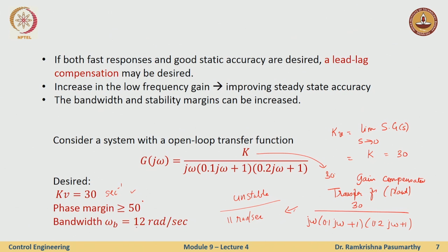So the specifications are usually in terms of the closed loop bandwidth, and in the previous lectures we saw how closed loop bandwidth was in a way related to zeta with some kind of complicated formula. So this bandwidth of 11.8 radians per second is for the open loop. How does the closed loop bandwidth look? Well, typically the closed loop bandwidth is usually greater than the bandwidth for the open loop. So if this is 11 here, the closed loop bandwidth would be roughly about 13.